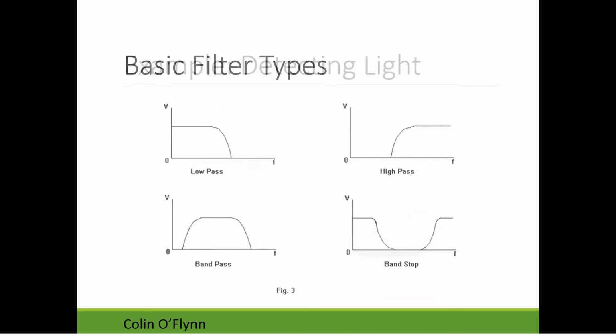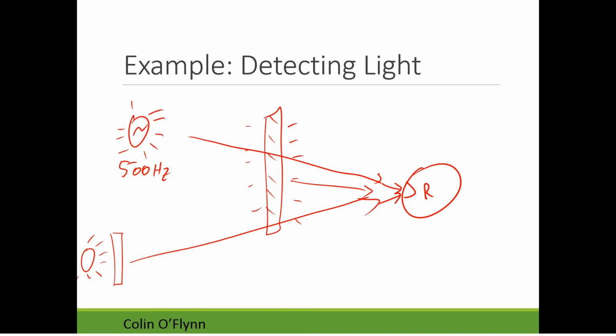So going back to this, one of the different solutions is you could make a high pass filter. And you could say, I'm just going to accept everything above, say, 200 hertz. And you might want to go a little higher, say 400. Why this would work is that the lights in the gym, if they're powered by AC, will probably be at 60 hertz. And sunlight is effectively DC, or 0 hertz.